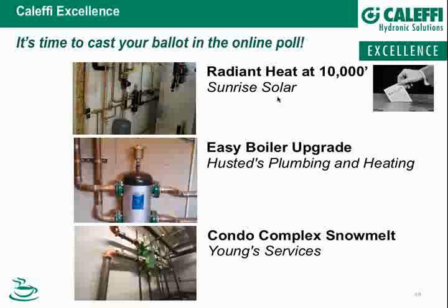But on the other hand, if you're looking for 10 and one of the curve crossings is giving you 14 or 15, you're probably spending more than you need to on the pump, and certainly it's likely you're going to spend more in operating that pump. Obviously, I'd rather err a little bit above as opposed to being a little bit low on the flow rate. But if somebody wants a number, I'll throw out plus or minus 10% as a guideline.